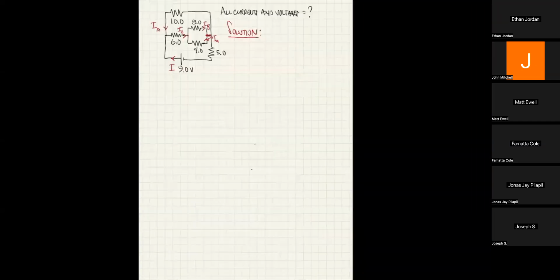Okay. So I'm going to first off eliminate the parallel resistors 8 and 4 ohms, because 1/8 plus 1/4 is equal to 1 plus 2 over 8, which is 3/8, which means the R equivalent for this one is 8/3, which is 2.667 ohms.